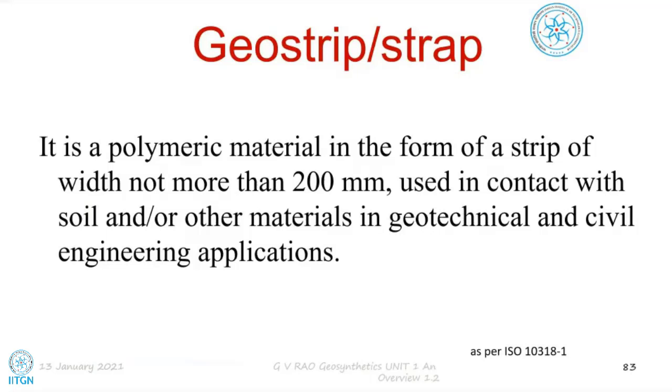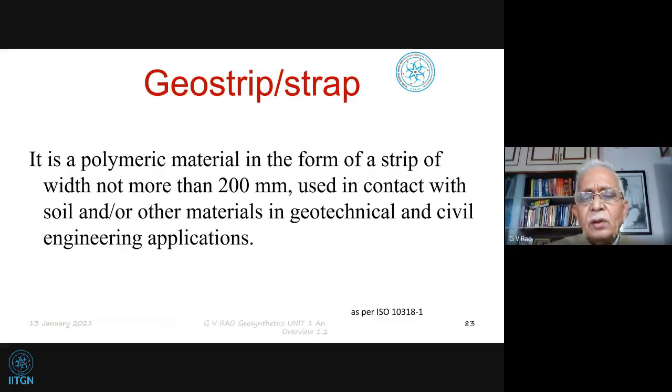These white pieces are actually polyester fibers. I forgot to mention that in the woven geogrid, the strength comes from polyester fibers, whereas the rigid grids are made of HDPE and PP. In the woven geogrids, we essentially use polyester fibers. So here also there's a bunch of polyester fibers. They are assembled together, and then put together as a number of assemblies.